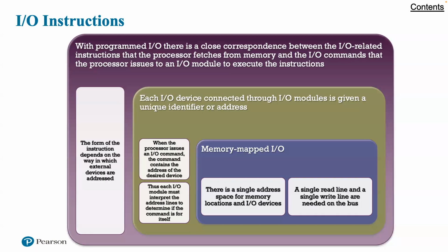The full range of addresses may be available for both. Again, with 10 address lines, the system may now support both 1024 memory locations and 1024 I/O addresses, because the address space for I/O is isolated from that of the memory. This is referred to as isolated I/O.